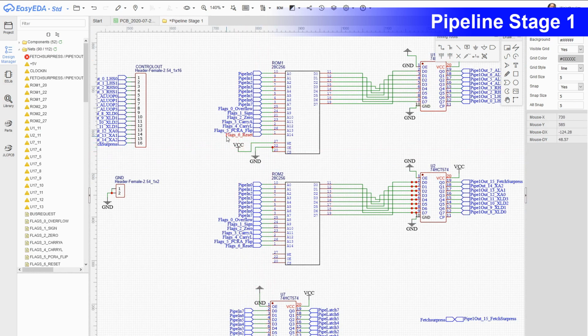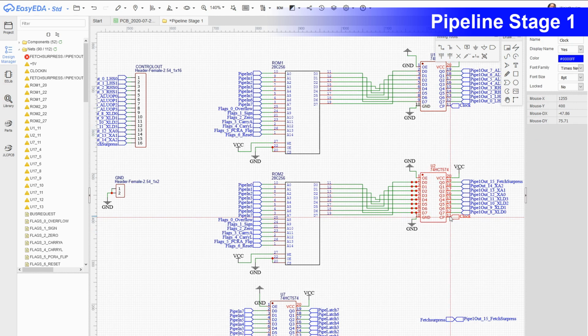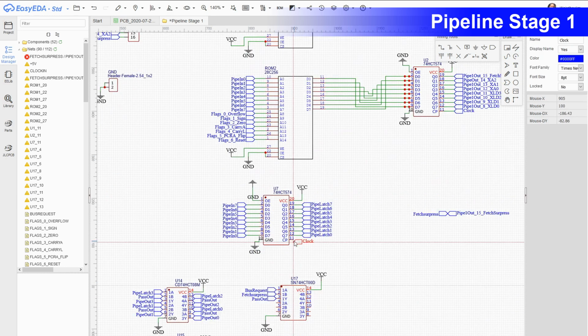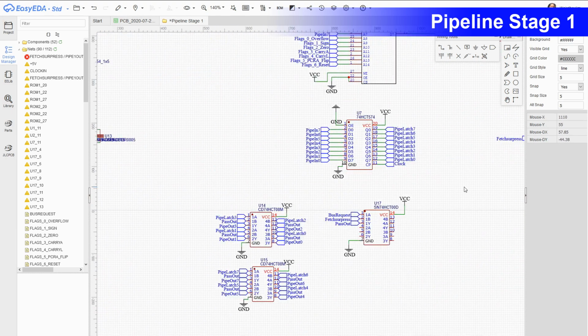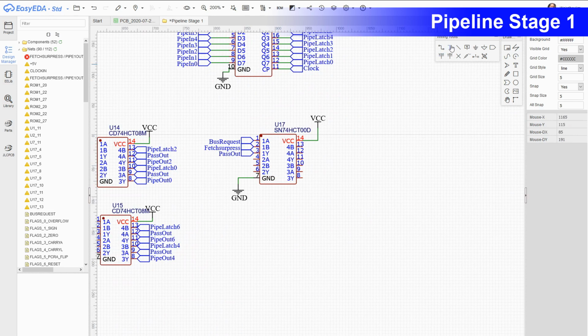On the breadboard, all of the clocks are driven from the same line in the entire pipeline, but we're right close to the fan-out limit for that signal. So a clock goes into 3 devices here. We've got NAND gates here that are unused. If we connect the inputs of a NAND gate together, it becomes an inverter. And if we stick 2 inverters in series, it becomes a buffer, albeit with a small delay.